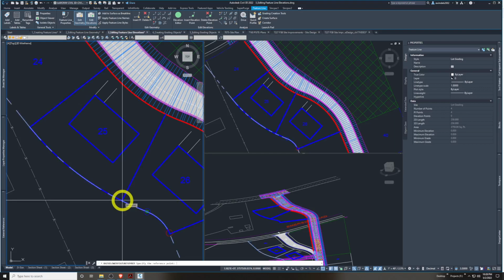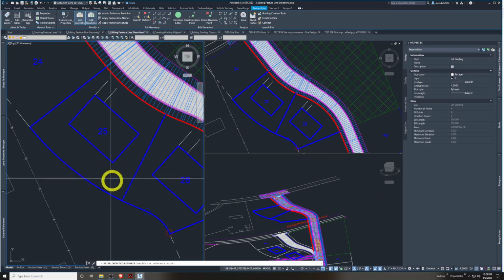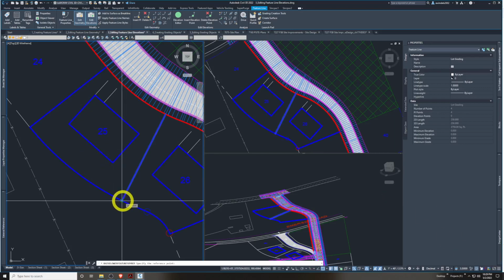Now, watch how different things are highlighting. The back lot, another line, my line in the middle here, which goes to 190.45, some change. That's what we want. So keep tabbing around. Look back here, okay? This is what it's wanting you to look at, the coordinates. If you don't have it, turn on your coordinates through your hamburger button. But let's hover here. Keep hitting tab until you see that 190.45, okay? Do it one more time. All right.